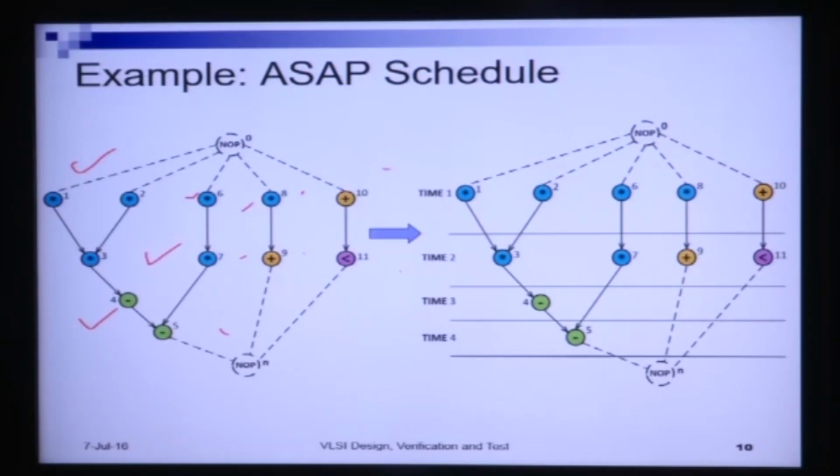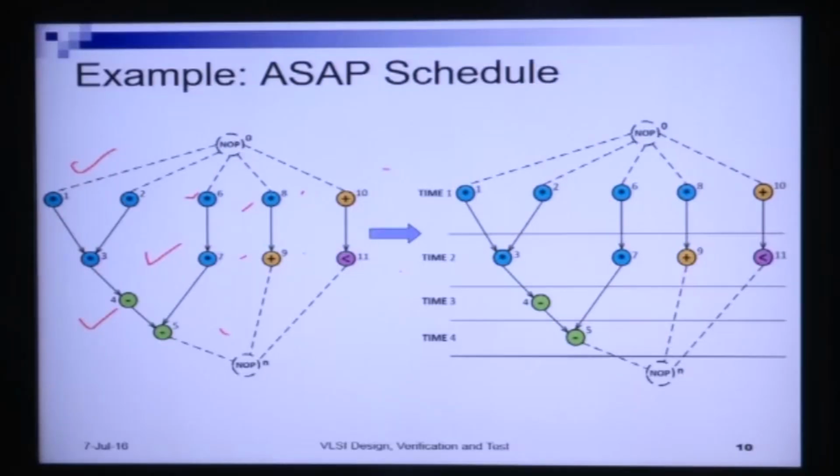So we will therefore get a very fast performing basic block if we do an ASAP schedule, but obviously we need unlimited hardware. For example, in step 1 we require 4 multiplication operations, and if we had a multiplier that performs these operations, we need 4 multipliers, because 4 multiplication operations are being performed concurrently in step 1, and hence the area of the obtained circuit will be high.